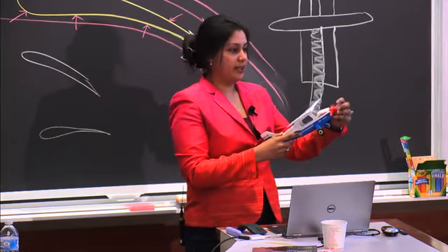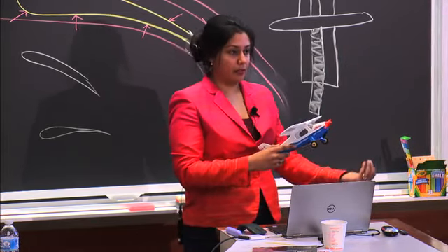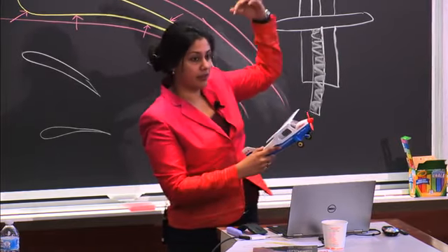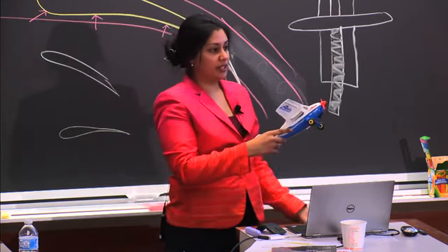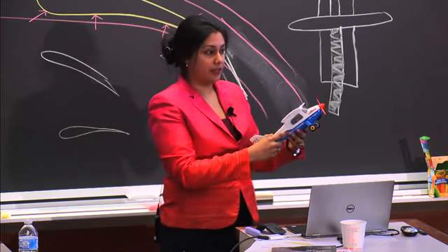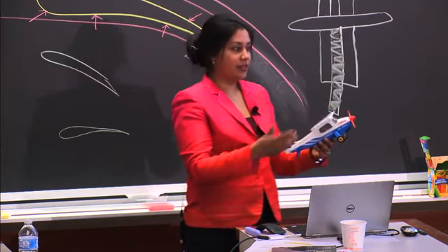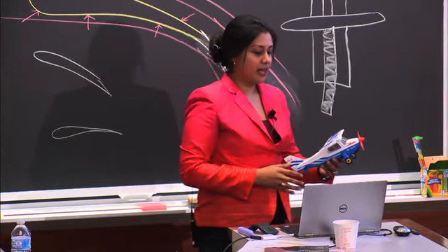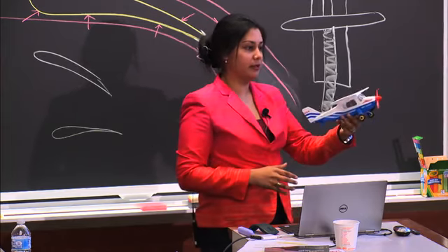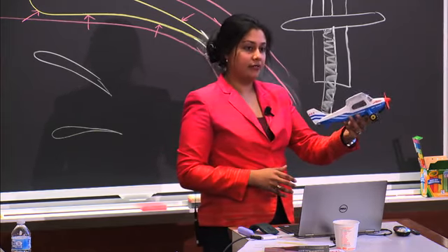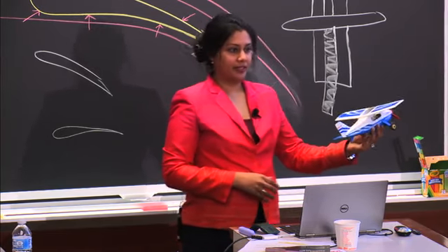Whereas the ascending left propeller blade, the blade that's going up on the left side, is coming away from the wind that's coming at it, and so it's not generating as much thrust as the right propeller blade. That causes the center of thrust to move towards the right, and that creates a little bit of a yaw tendency of the airplane. Does that make sense?